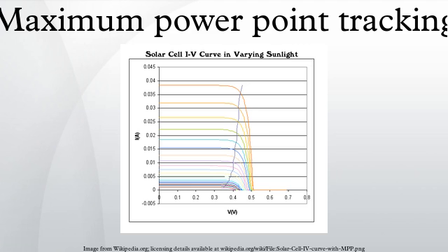Maximum power point trackers utilize different types of control circuit or logic to search for this point and thus to allow the converter circuit to extract the maximum power available from a cell. Classification. Controllers usually follow one of three types of strategies to optimize the power output of an array. Maximum power point trackers may implement different algorithms and switch between them based on the operating conditions of the array.